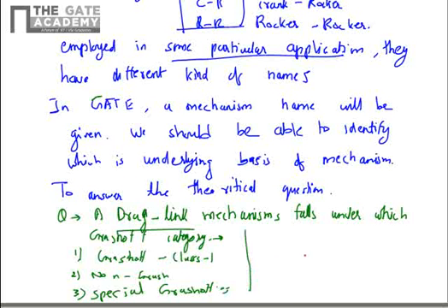The drag link mechanism is basically a double crank mechanism. But the special thing about this double crank is that it's not like a parallelogram double crank that we just discussed towards the end of the last video. In a parallelogram double crank, you get the same circles, same motion is getting transmitted. But in a general double crank, the motion of the two cranks may be different.